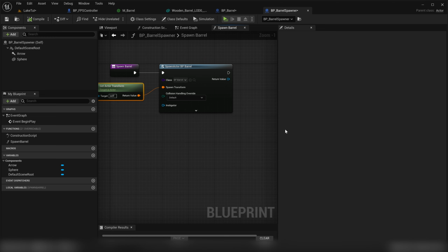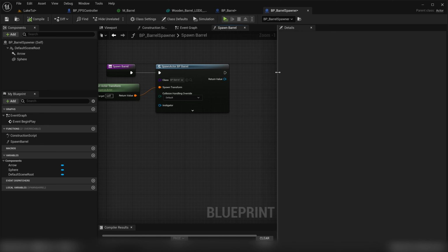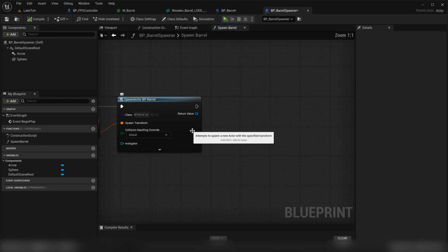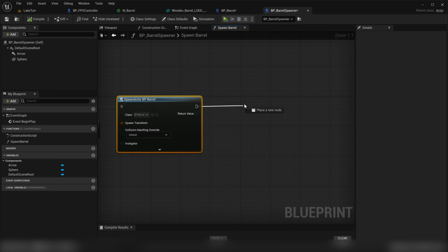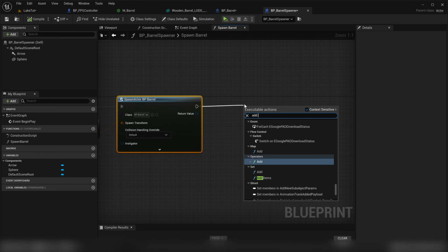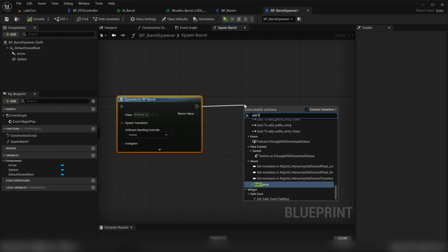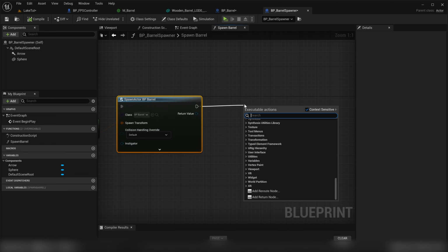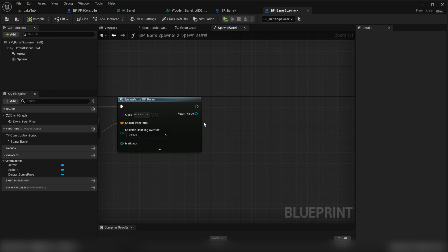So what we're going to do is add an impulse, and an impulse is like a one-off, one-shot application of force in Unreal, whereas an actual force, because we do have like add force, is a constant slower force. So for this case, we just want to get a bit of an initial movement, so we're going to use an add impulse.